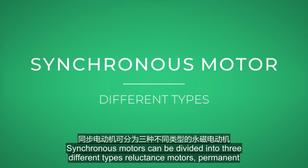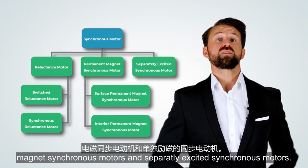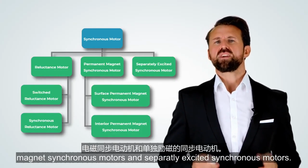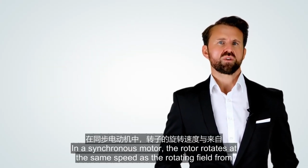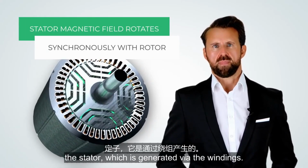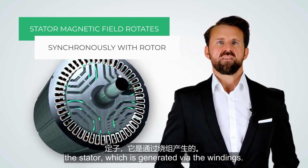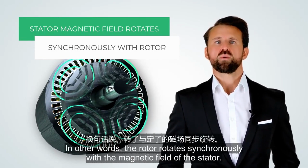Synchronous motors can be divided into three different types: reluctance motors, permanent magnet synchronous motors, and separately excited synchronous motors. In a synchronous motor, the rotor rotates at the same speed as the rotating field from the stator, which is generated via the windings. In other words, the rotor rotates synchronously with the magnetic field of the stator.